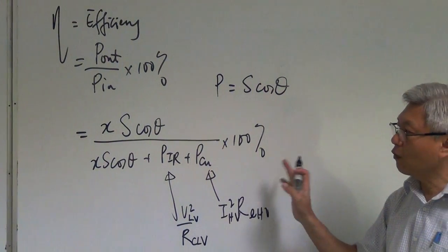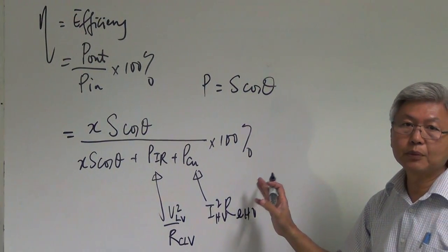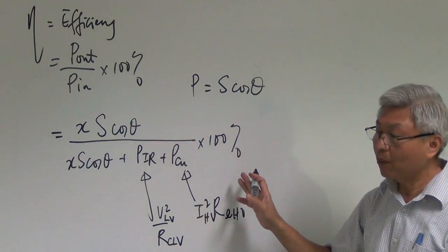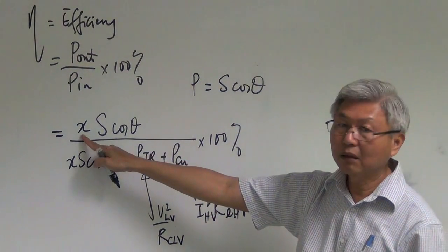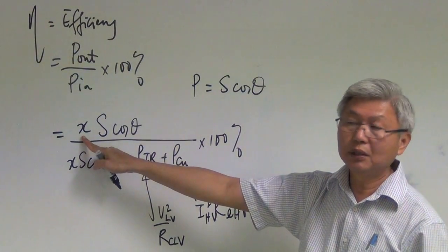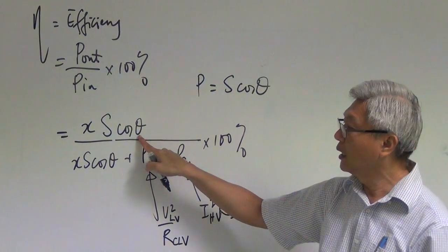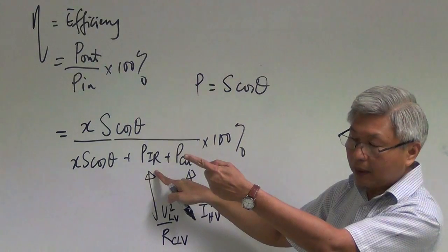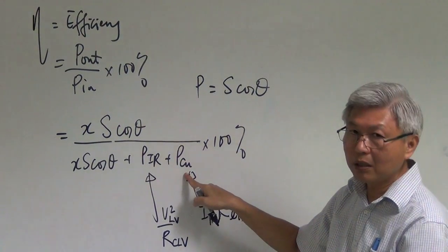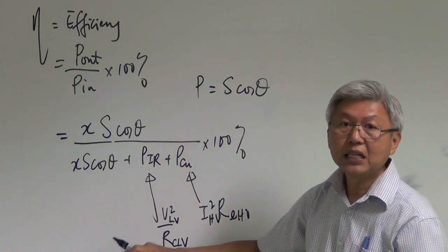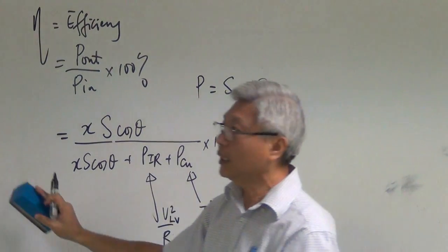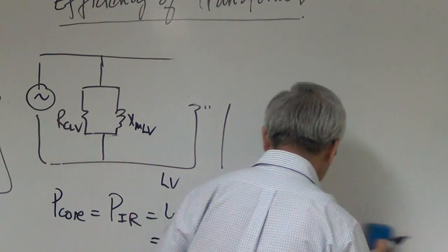Efficiency of the transformer. This formula is provided in the exam. But you must understand what it means. What does this mean? Fraction of full load. This is the apparent power. This is the power factor. Yeah? Iron loss, the power that happens in the parallel circuit, copper loss, the loss that happens in a series circuit. Alright? Now let's continue a little bit more on the efficiency.